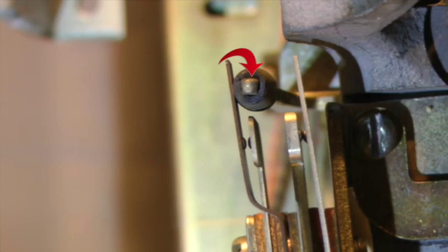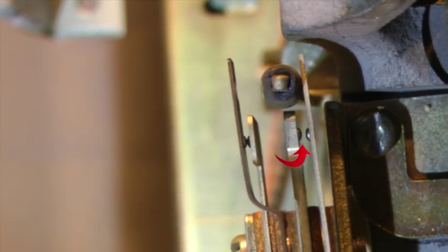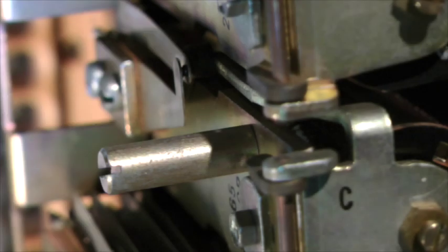The rotary interrupter arm, attached to the rotary armature, operates, closing make contacts 3 and 4 and opening break contacts 1 and 2. This opens the operating path of the C relay, which now releases.